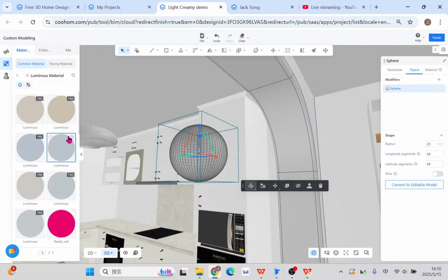If you have this symbol, it means these are all controllable, or even if you turn to the real-time rendering, you also have the last chance to control the light effect, the strength, how strong the light is, or the color temperature before you go to the final render.